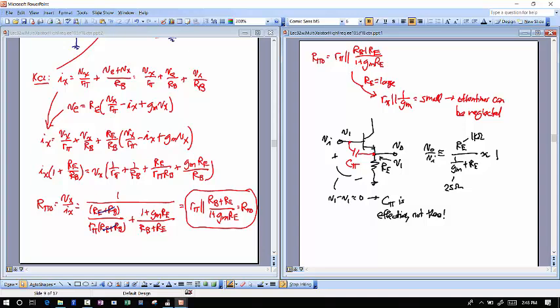If you see this, you can either memorize that equation. I have it memorized in case I have. Now you can't do this if there aren't other dominant time constants in other places. If you have no other dominant time constant, you better know this equation here. But if you know that there's some Miller effect going on and some big resistance across that Miller effect, neglect this capacitor.